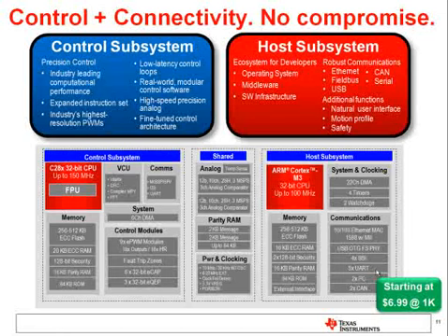Customers who are heavy on the control side will likely choose to partition the RAM to the C28X core, while customers who need to do more communication can choose to dedicate more RAM to the Cortex-M3 side. Concerto also includes shared analog because safety is becoming more important in green applications, and this configuration allows each core to check inputs from the ADC. We'll talk more about safety a little later in this presentation. There are no special power or clocking requirements for Concerto, so it's just as friendly as the Piccolo power and clocking scheme. Basically, it has all the conveniences such as a single rail supply with an internal voltage regulator, internal oscillator, and clock fail detector.